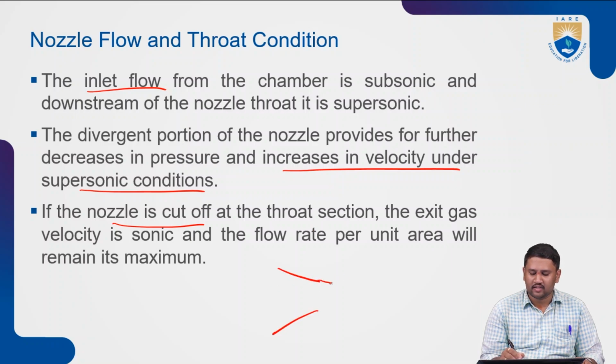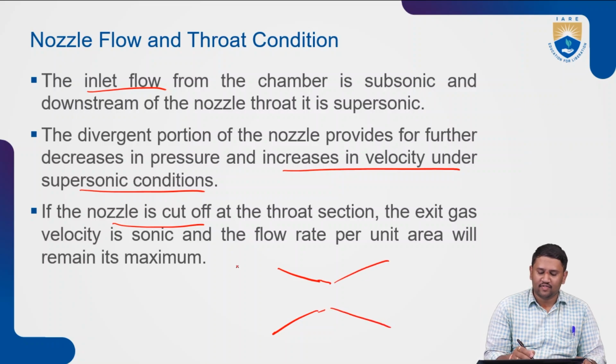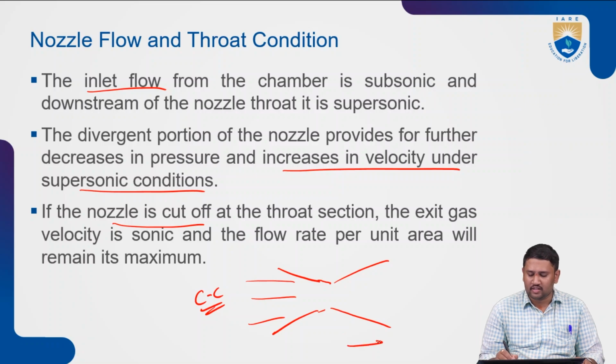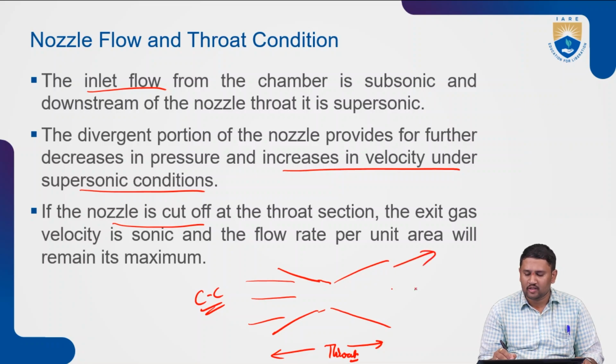Let me just draw it a bit. Now, the inlet flow from the combustion chamber is subsonic, right? Whereas downstream of the nozzle, the flow will be supersonic.